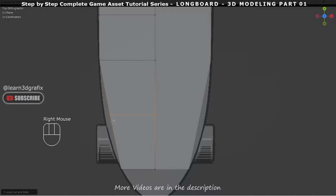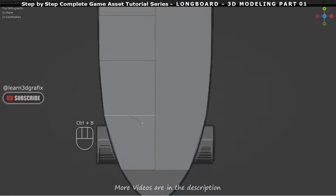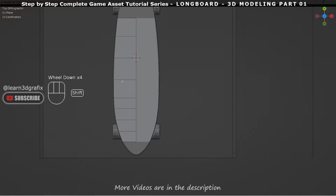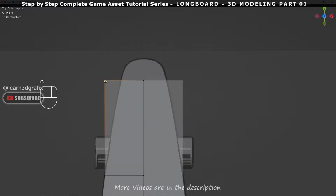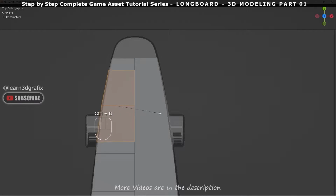Press Ctrl R to insert an edge. Now select the edge and press Ctrl B to add multiple edges. Now select this edge, press E and Y and extrude it on the top. Press Ctrl R to insert an edge. Now select the edge and Ctrl B to add more edges.